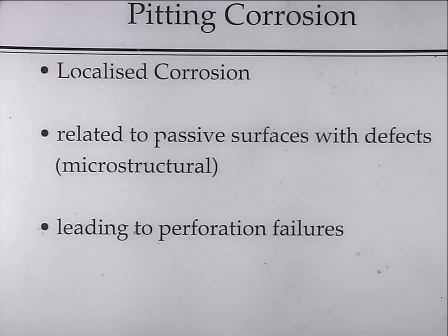But if you've just been inspecting the pipe routinely further along, you would have said, oh yeah, this pipe's fine, you know, there's plenty of wall thickness there, not a problem. So you've got to be very careful when you're trying to hunt for localised corrosion failures.